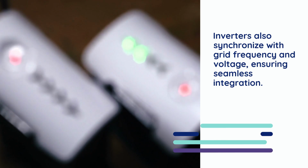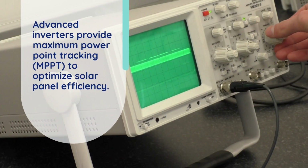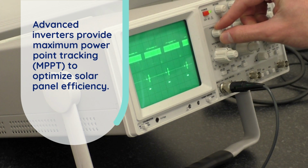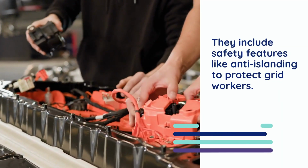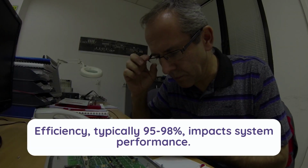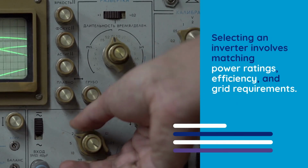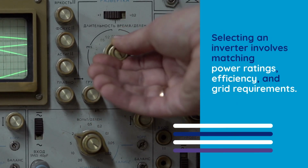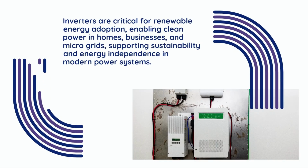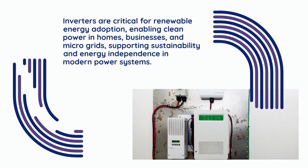Inverters also synchronize with grid frequency and voltage, ensuring seamless integration. Advanced inverters provide maximum power point tracking, MPPT, to optimize solar panel efficiency. They include safety features like anti-islanding to protect grid workers. Efficiency, typically 95 to 98%, impacts system performance. Selecting an inverter involves matching power ratings, efficiency, and grid requirements. Inverters are critical for renewable energy adoption, enabling clean power in homes, businesses, and microgrids, supporting sustainability and energy independence in modern power systems.